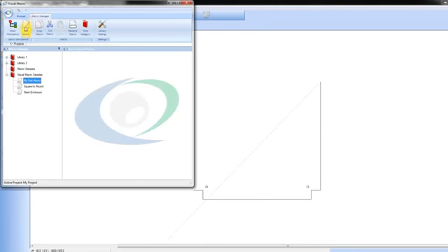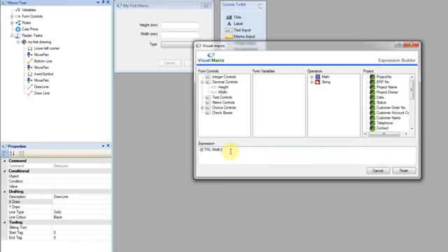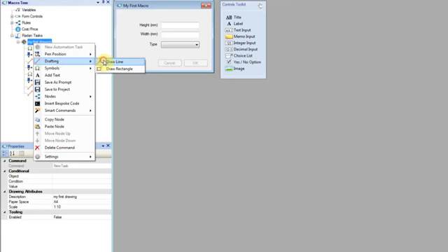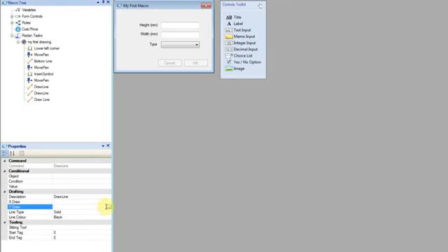This value is the sum of the two Move Pen commands, and the width value. The value has a minus because we are drawing in a backwards direction. Next add another Draw Line node and set it to draw in the Y direction by -height.